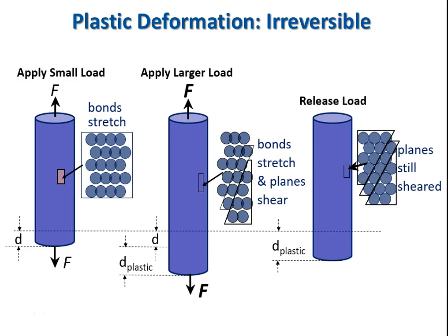So if we go back to our handy uniaxial tensile bar that we started with at the very beginning of the elasticity section, and we apply that same load per unit area, which would be our sigma normal tensile stress, and we deform an increment d just like we did before, we'll see that once again our interatomic average spacing goes beyond equilibrium. Bonds stretch effectively, as is shown over in the left-handmost diagram.